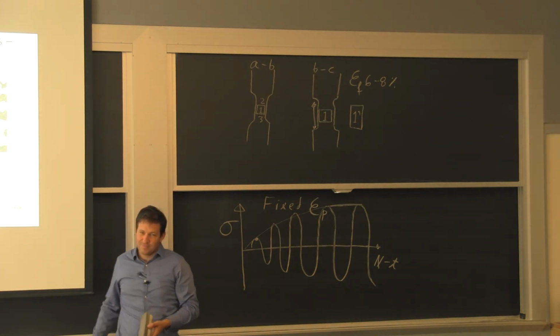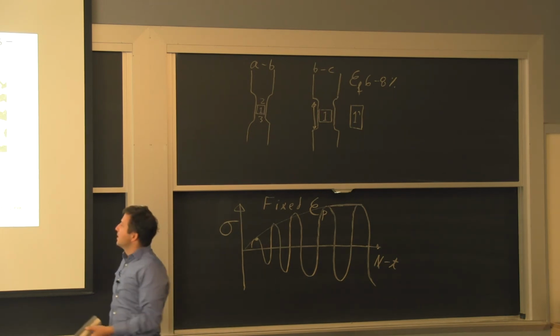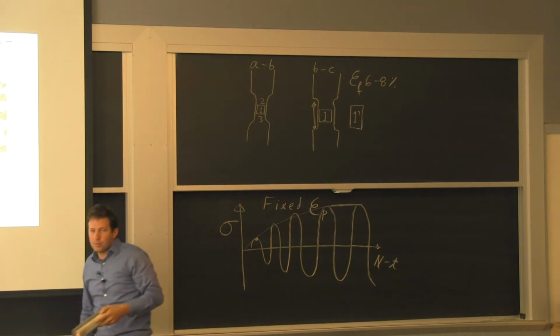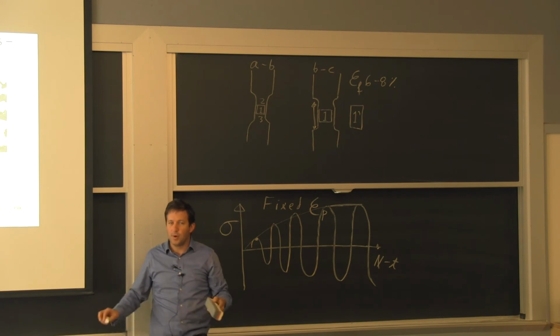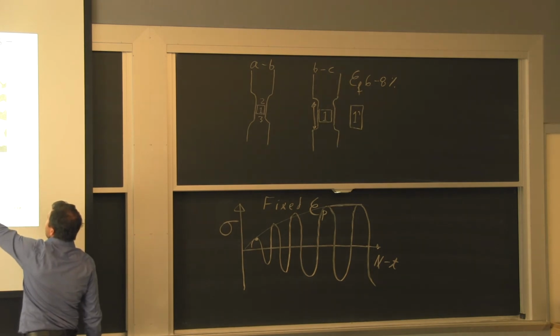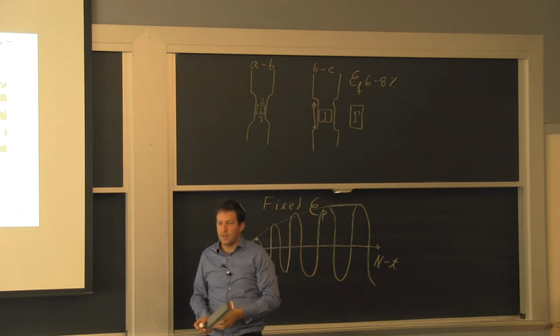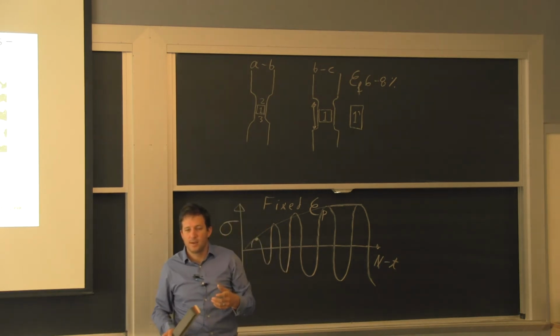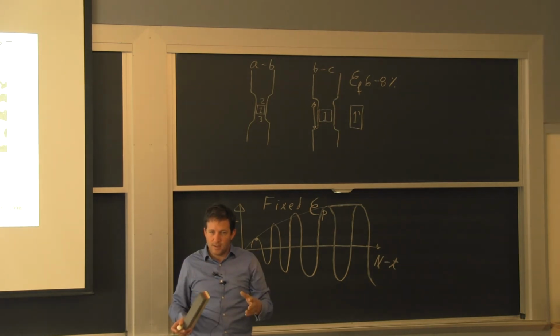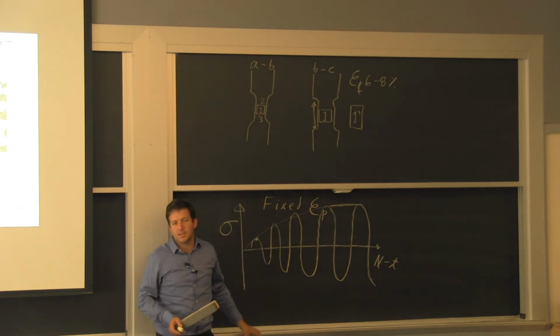Just go ahead. Would you mind just explaining what gives rise to the black and white regions? Black is a high density of screw and edge dislocations, and you have both of them. Now, there will be some very detailed studies that will tell you that those are mostly edge, some are mostly screw. I can't remember which one is which. But think of it as one grain that has all these internal defects that act as your mechanism for being able to deform back and forth. You're imposing a plastic strain here.